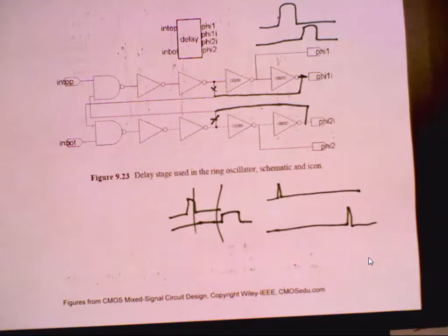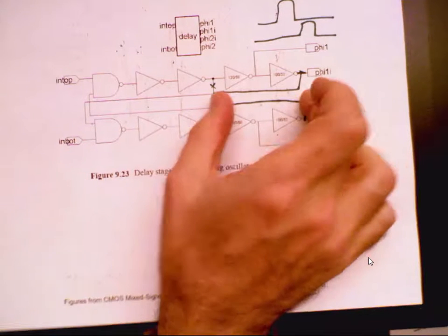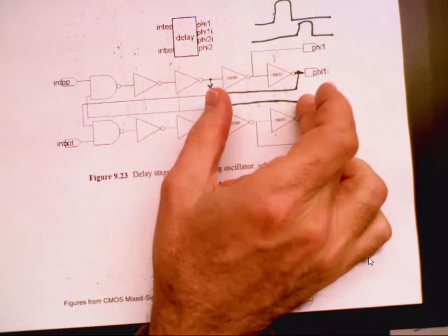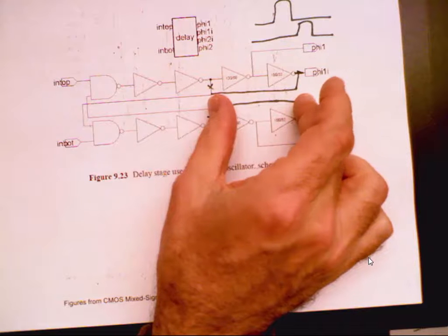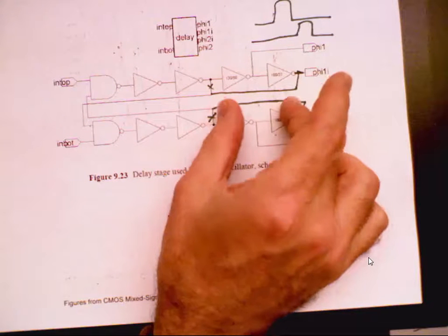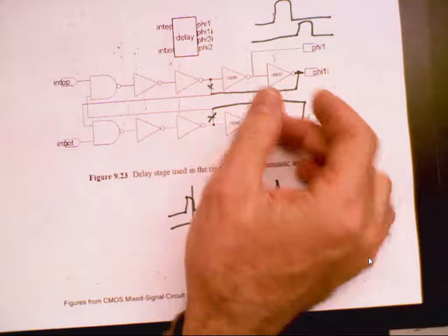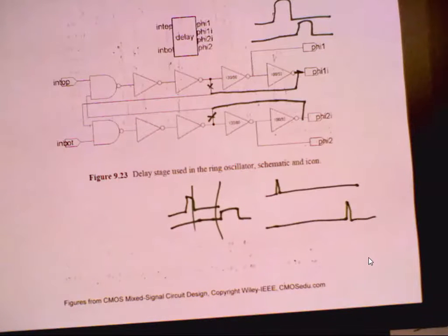I think if you're going to try and use transmission gates, you'd want those edges to be really decisive. Yeah, you want them to be fast, and you want it to turn things on, and feed back a nice square signal, so you want as much drive as you possibly can. And I think that's fine. It's just that if you needed a 50% duty cycle, you should know it makes it less 50%. It's not a problem, and I did it for this reason.